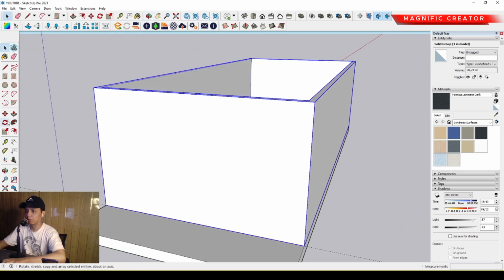opening. We can make the opening by selecting the measure tool. Then we can set it up around 2400 millimeters, and then make the side wall thickness around 600 millimeters. I'm sorry, I repeat, around 600 millimeters, and from the left to the right 600 millimeters also.